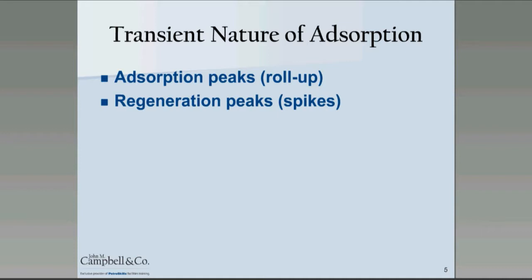It's usually not a big issue in adsorption, but you really do need to be aware of this. For example, if you're using a type 5A molecular sieve, which will admit lots of hydrocarbons into the pores, you may see a hydrocarbon spike in the outlet. This could cause issues in your downstream operations if they happen to be sensitive to hydrocarbon peaks.